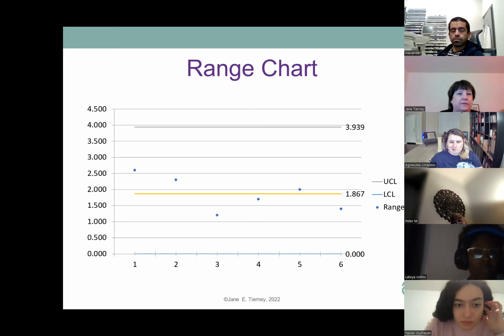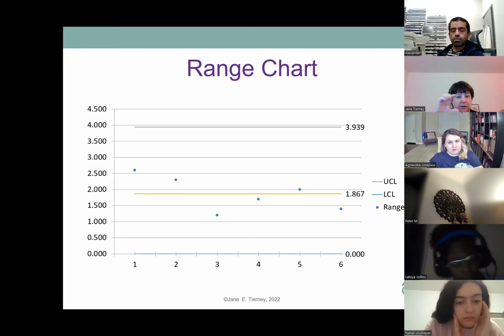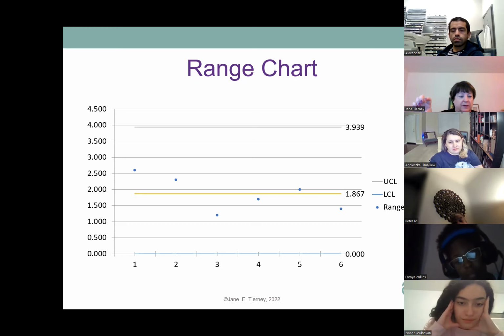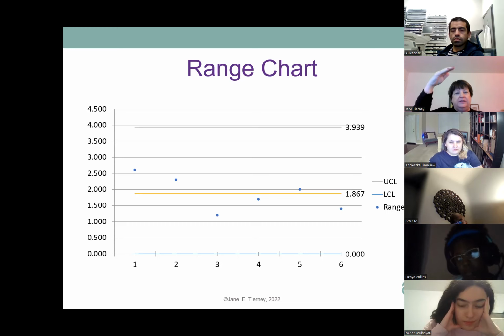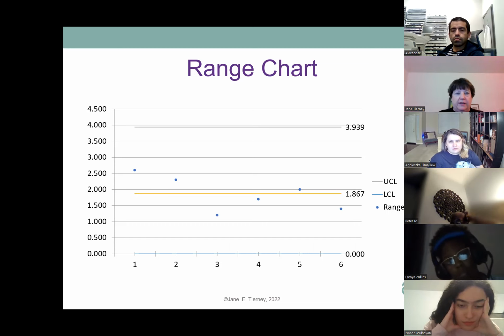And then we have formulas where we calculate upper and lower control limits for ranges as well. So this is the range we want to stay within. If we see something that's way bigger than that, smaller than that is not a problem. But if we see something that's way bigger, then we say, okay, now we have something going on with this process. So we're losing control. We're not going to be in control on this process, and we've got too much variation.